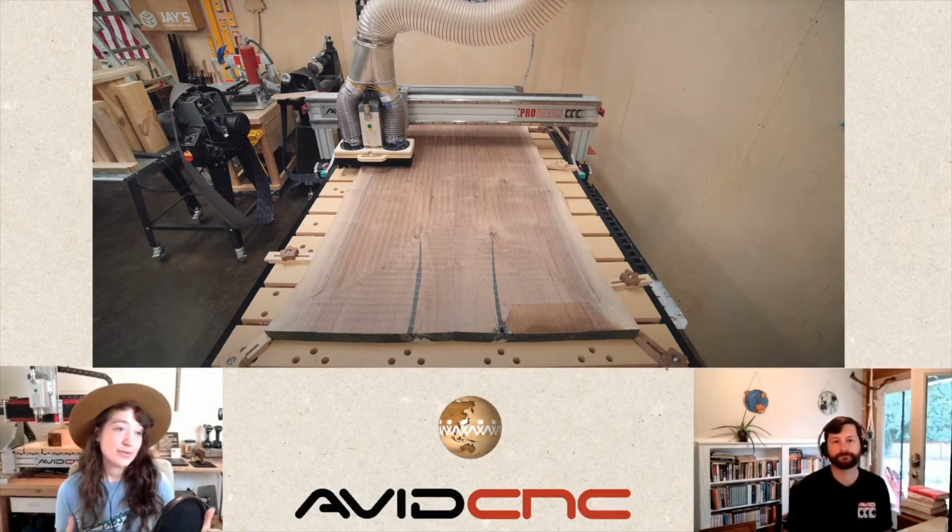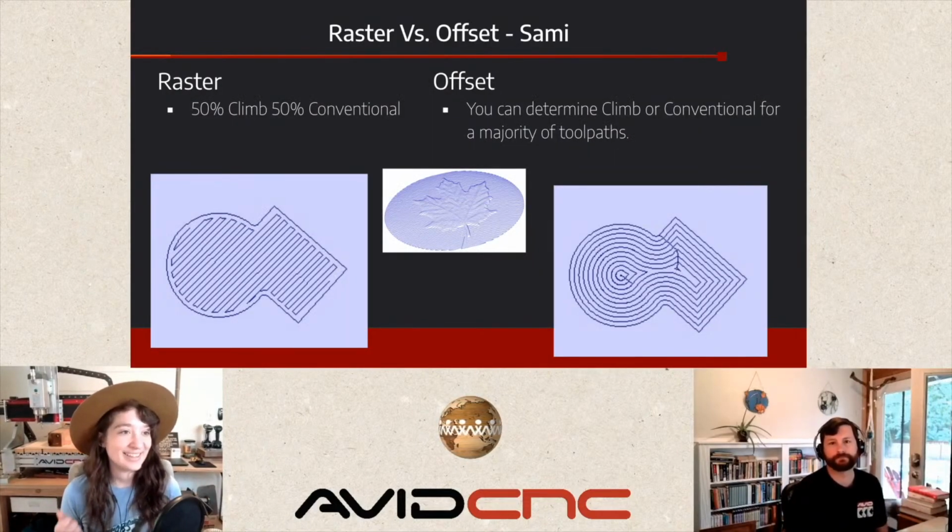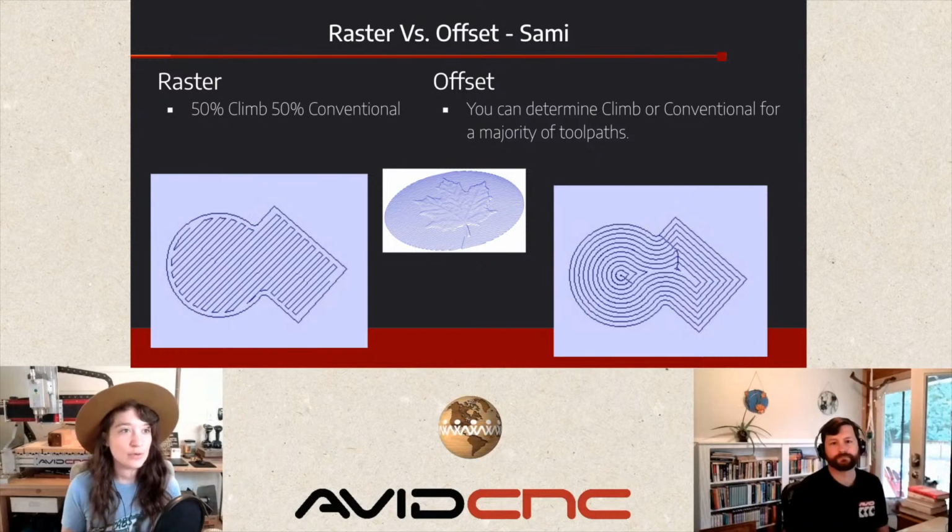Yeah. So that also kind of brings us into raster versus offset. This is an option that I like to consider, especially when you're looking at the vectors and the geometry that you're being limited by. Vectors are a fixed variable because that's really dictating the end goal here. Raster I like to use if it's something rectangular that we're trying to achieve, but if there is some sort of odd shaped geometry that we're trying to conform to, I tend to prefer the offset.